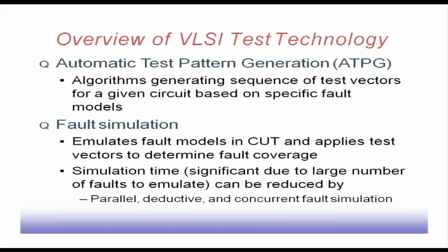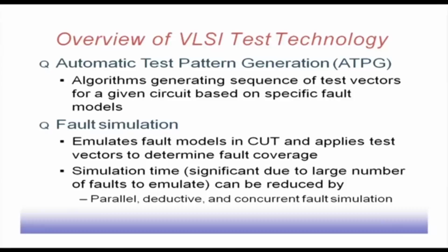Naturally, the question is the simulation time. How much time does it need to do the simulation? If I have, say, 100 test patterns and 100 faults, and I am simulating the system for each fault and each test pattern, that means the entire circuit has to be simulated 100 into 100 times. That is a huge number. So, can we reduce this time? When we go to fault simulation techniques, we will see that there are several techniques by which we can do this, say parallel simulation, deductive simulation, concurrent simulation, over and above the very simple serial simulation.